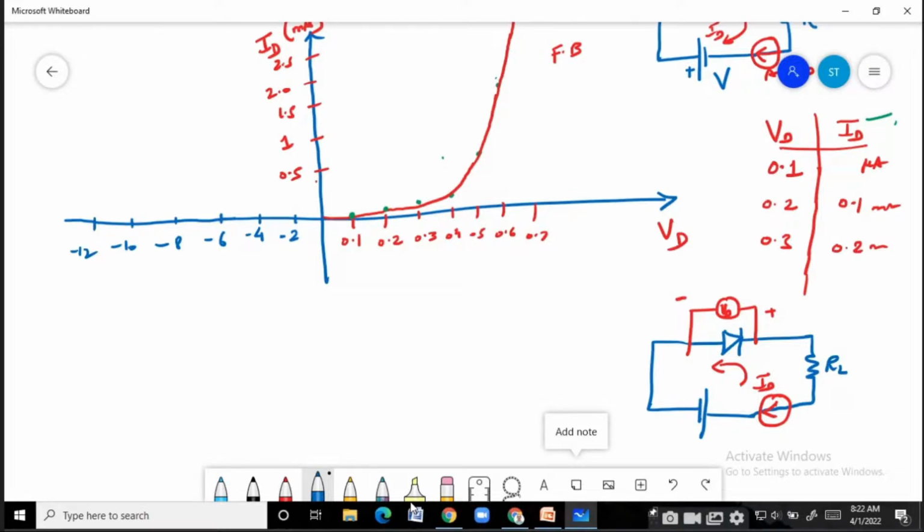You get a table like this. So you increase the voltage across the diode to 2 volt. You measure the diode current. So you get a certain point. Suppose you get a point over here. Then you increase it to -4, and there is not a significant rise in current. Also, in the reverse bias condition, your scale is going to be in microamperes. You have to remember this, otherwise you will not get a correct plot when you are plotting a graph.